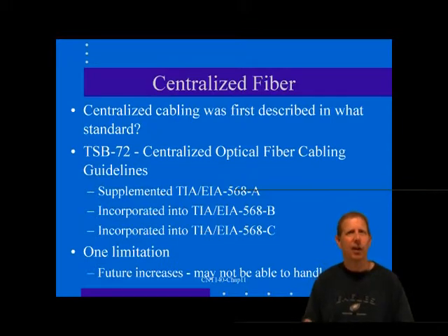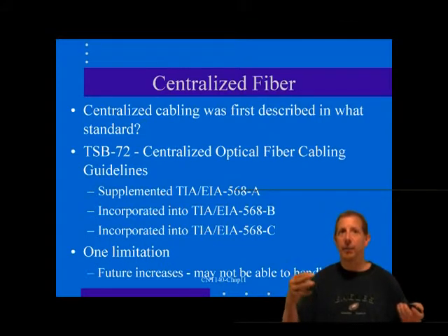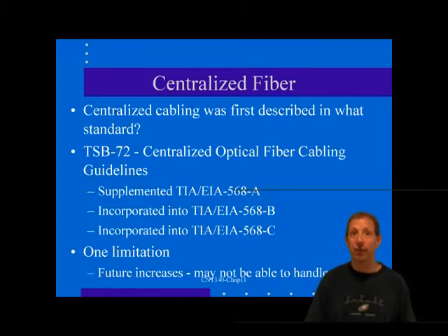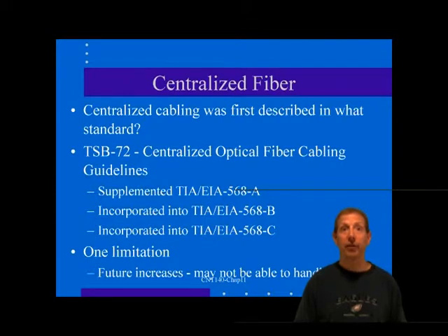Remember that the current crop of legacy fiber in the horizontal cabling is miraculously able to support gigabit because of the short horizontal limit of structured cabling. Newer, laser-friendly multimode and single-mode cable is still overkill at 90 meters for gigabit, but it might be just right for 10 gigabit operations. A measure of future proofing can be obtained by at least running your centralized fiber through a TR. Then, if you absolutely must have shorter fiber runs to support future technology, you can cut and terminate the fiber runs within the TR and place your hub equipment there.